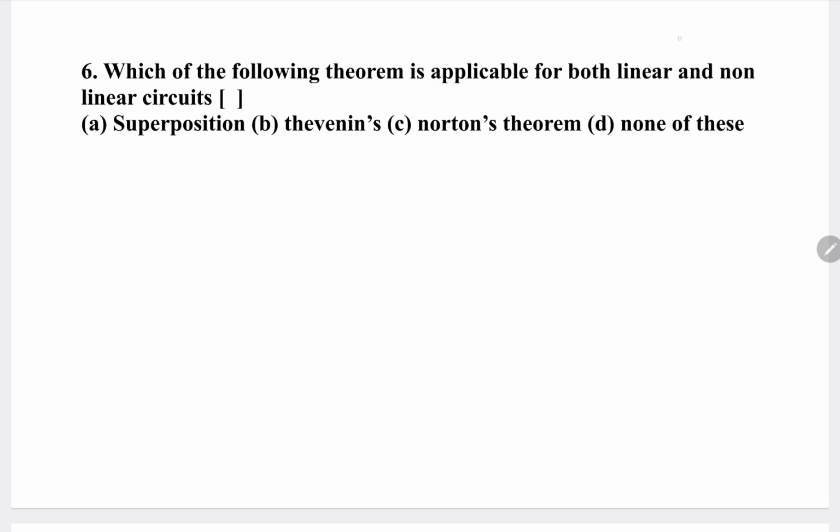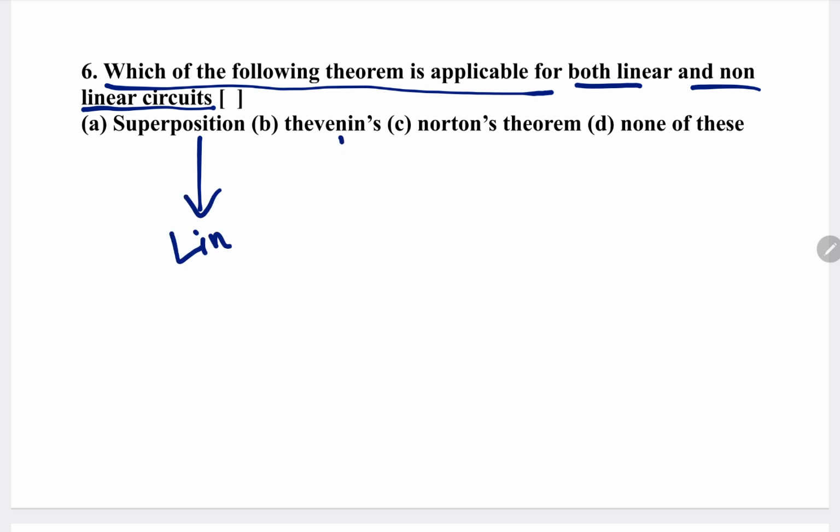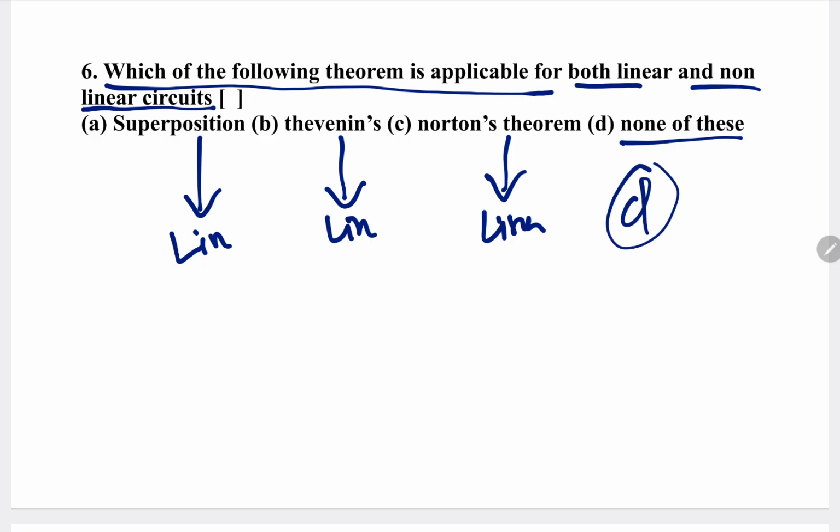Next, sixth question. Which of the following theorems is applicable for both linear and non-linear circuits? The superposition theorem is applicable to only linear circuits. Thevenin's theorem is also applicable to linear circuits. Norton's theorem is also applicable to linear circuits. But the question asks which theorem can be applied to both linear as well as non-linear circuits. So, none of these. The superposition theorem, Thevenin's theorem, and Norton's theorem are all applicable to only linear circuits.